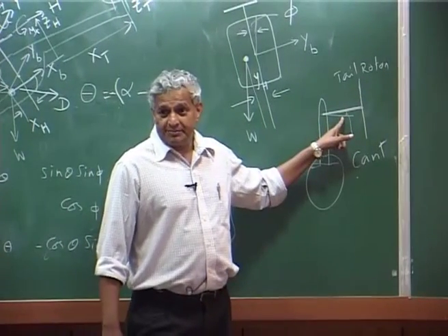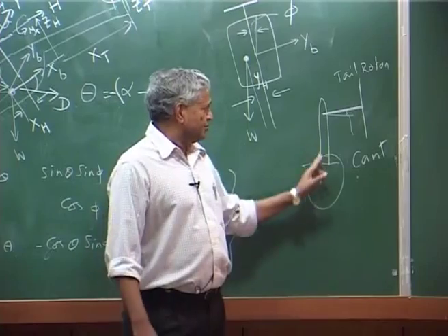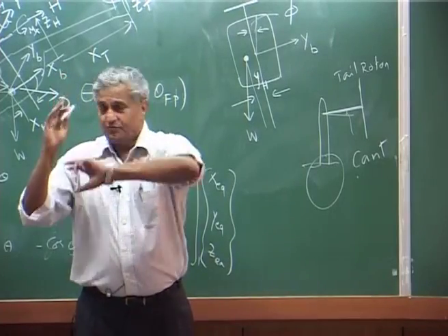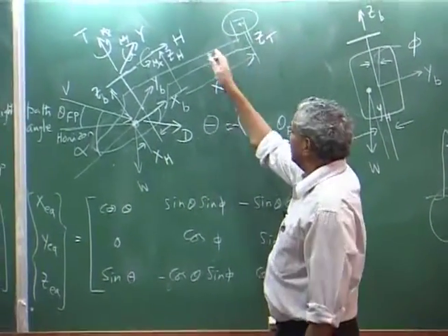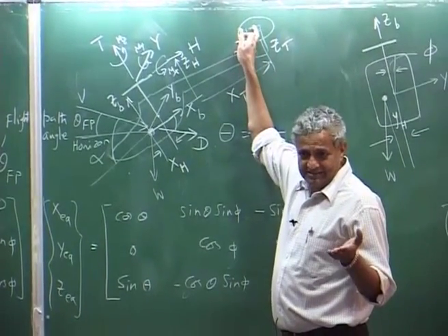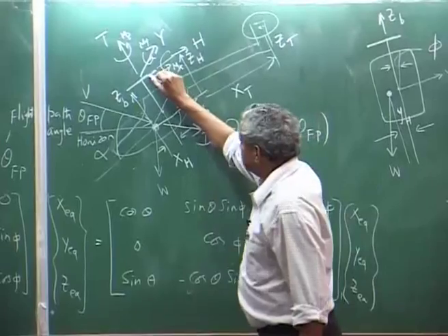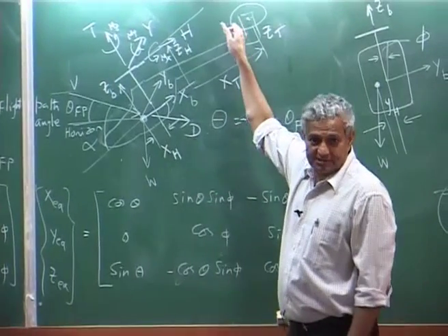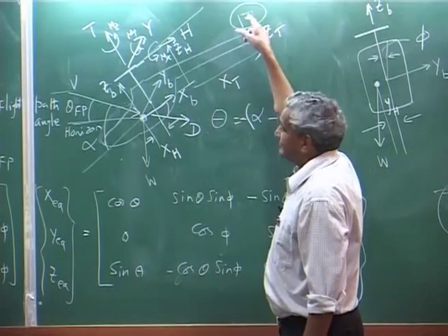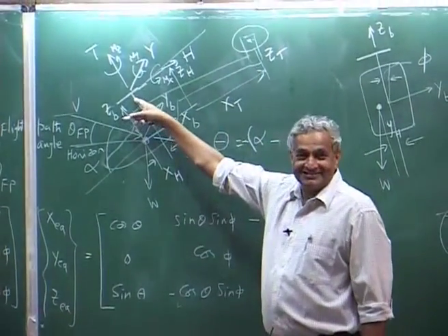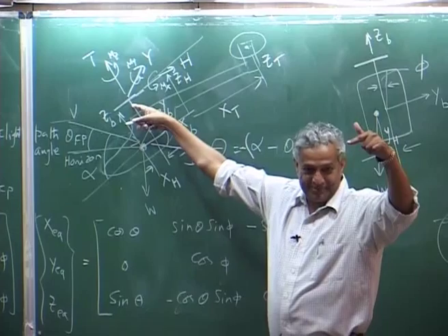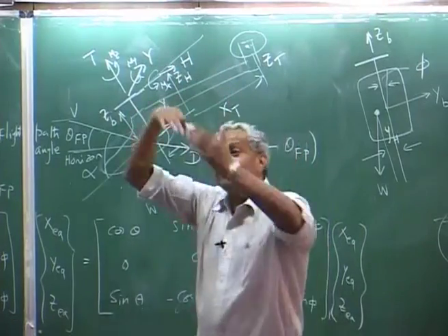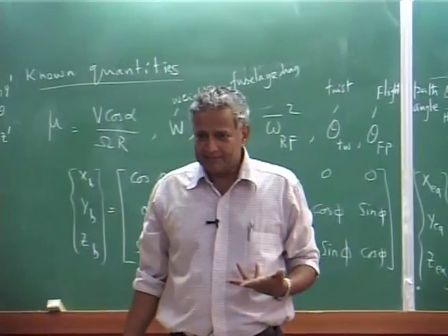This is mounted, because first of all the vertical fin you need, because if you want to mount the tail at a slightly higher position from the boom, because you may ask why I have to shift it up, that is like a configuration, because of the main rotor wake, you do not want it to go and hit the tail rotor. So, you try to keep this center along this height, rotor hub height, so that the tail rotor is not affected by the flow from the main rotor. If it gets affected, you do not know what is going on.